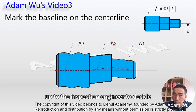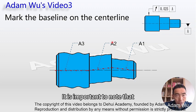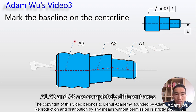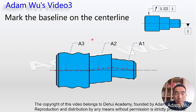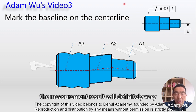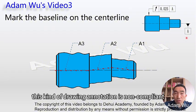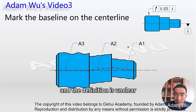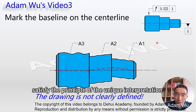Should we leave it up to the inspection engineer to decide? It is important to note that A1, A2, and A3 are completely different axes. If we select different axes as the datum, the measurement result will definitely vary. Therefore, this kind of drawing annotation is non-compliant, and the definition is unclear. It doesn't satisfy the principle of the unique interpretation for the drawing.